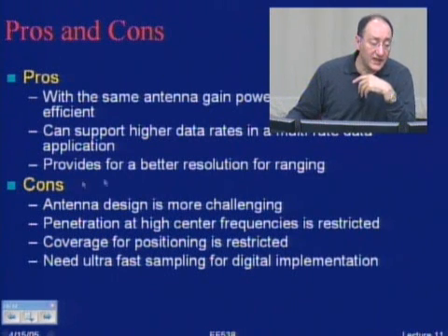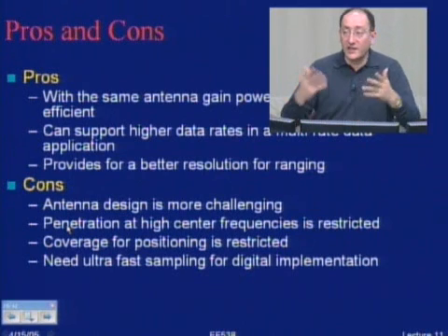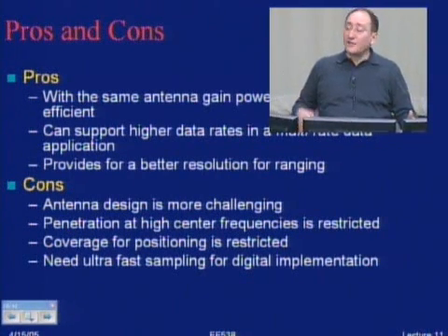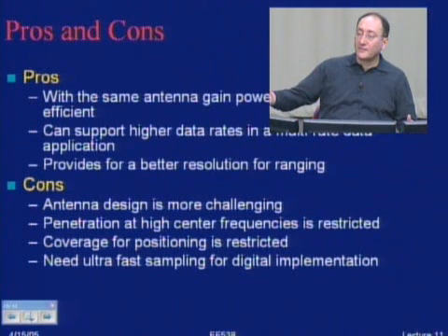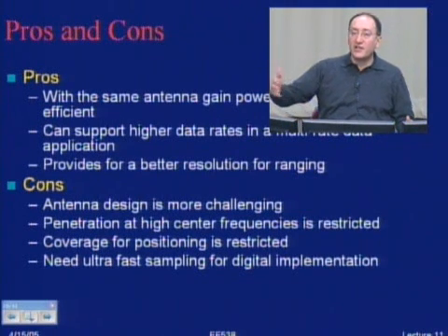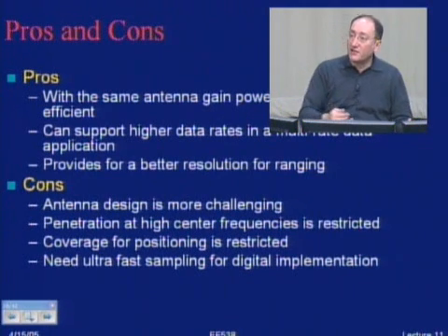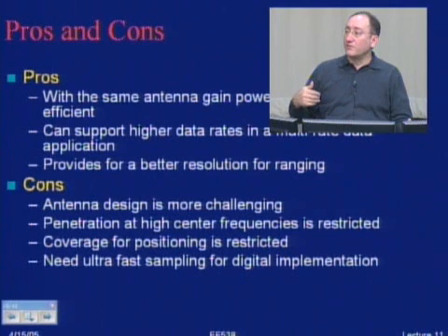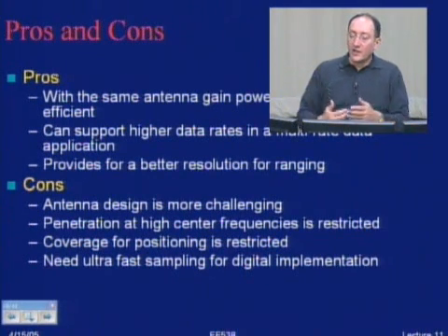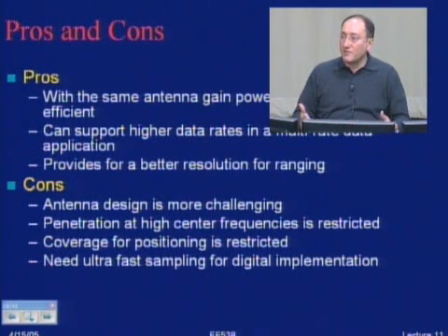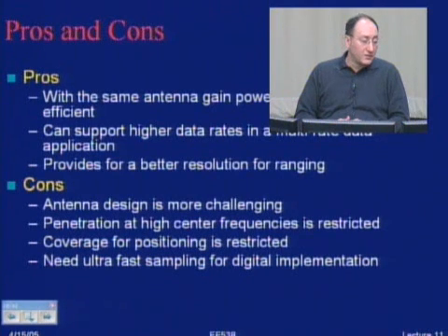The second issue is that if I want to go to those gigabit type of bandwidths, I have to go to higher frequencies. If I go to several gigahertz as my center frequency, then penetration through the walls becomes less. So in most of these applications that I'm talking about, WPAN, my coverage becomes limited.